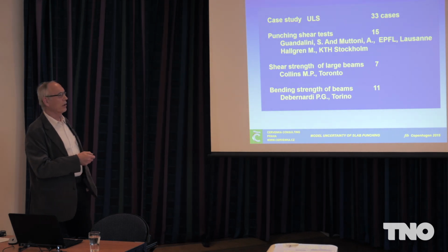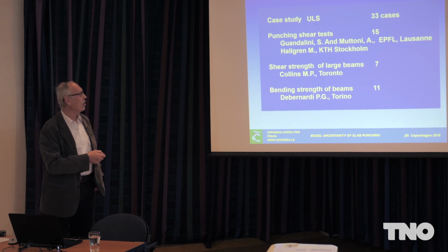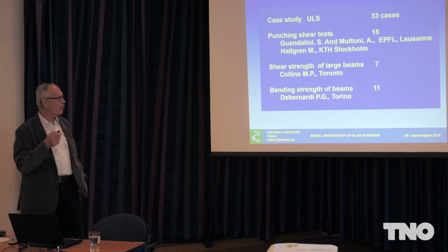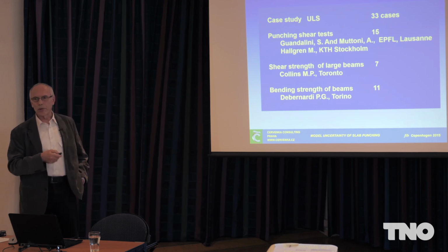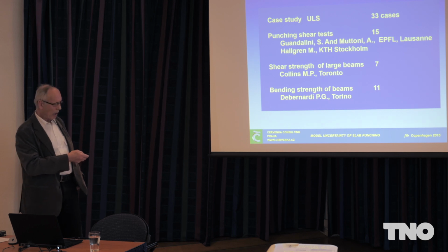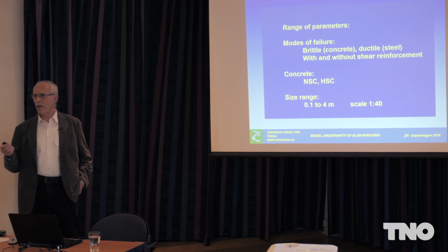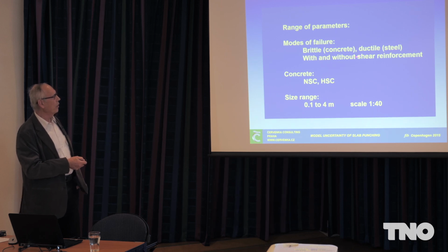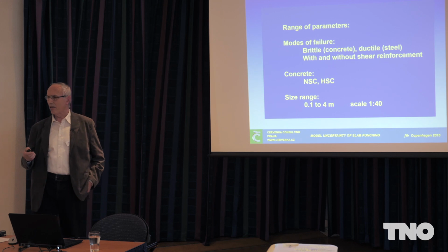So I'm talking about this group of tests. We have 33 cases, punching shear tests. We have shear strengths of beams, basically large beams, and we have bending of normal beams to describe also the usual design situations. And the range of parameters is rather large. You see we have brittle modes of failure, ductile modes of failure, with and without shear reinforcement, also in brittle modes of failure, concrete, higher strengths, normal strengths, and most important, the size effect is there.